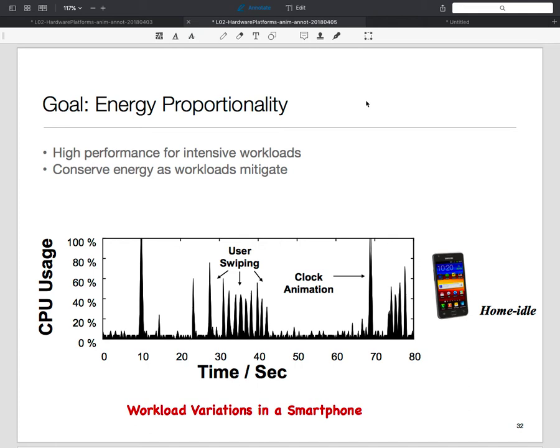These are exactly the kind of things you find when you read the data sheet. I usually find the most interesting systems of an MCU, since a processor is a processor and doesn't really matter, are the timer system, where all the timer stuff is located, and the power management. I think these two are very interesting and useful to understand about a particular device. Now, the other thing is that not all capabilities of the hardware may be exposed by the OS. Operating systems are designed for portability and general purpose usage, so some of these things you can exploit only when you are willing to write down to the hardware.